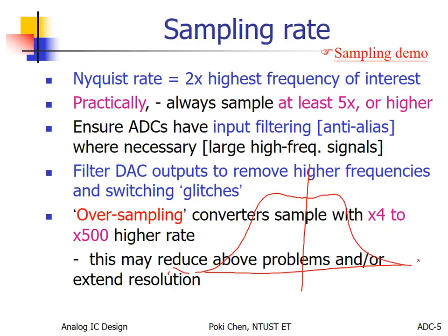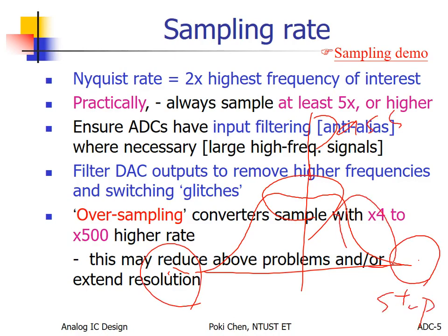It means what? This is what you want. We call it the pass band. And those you wouldn't like to have, we call it the stop band. And in between, we have the transition band. That is the practical situation. In theory, we hope the transition band to be 0, but in practice, forget about it. You cannot make it. In theory, the higher the order, the smaller the transition. Smaller transition means the slope will become higher and higher, so it will be more ideal.